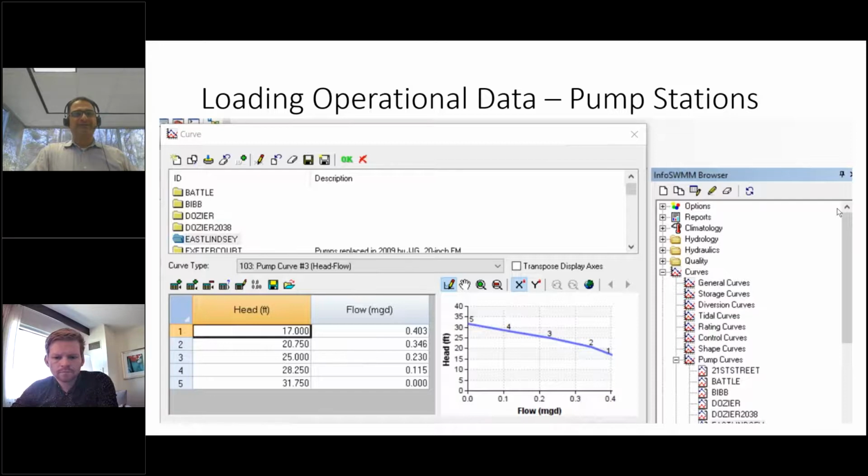If we have reason to believe that there is wear and tear, or if the client, the utility, the operator says something to that effect, like it never runs, we're never able to put out this or that, then we would request a drawdown test, or we would do it ourselves depending on our scope, and use those values.